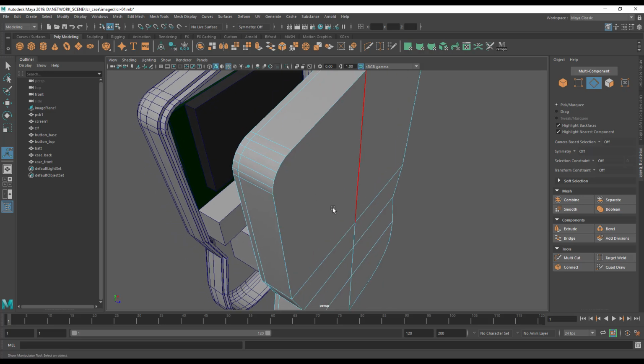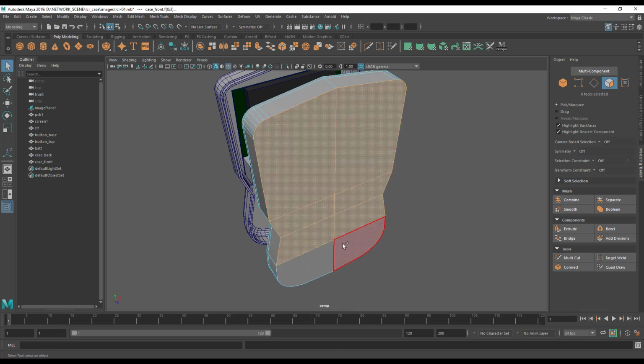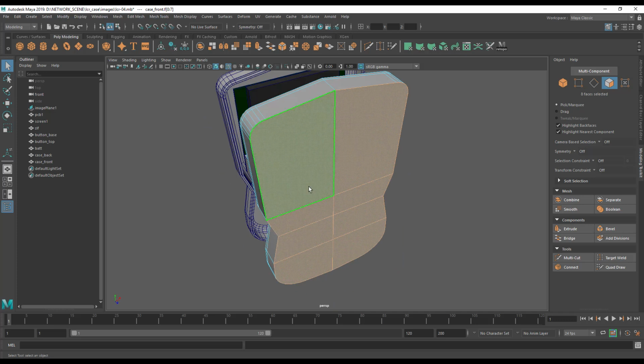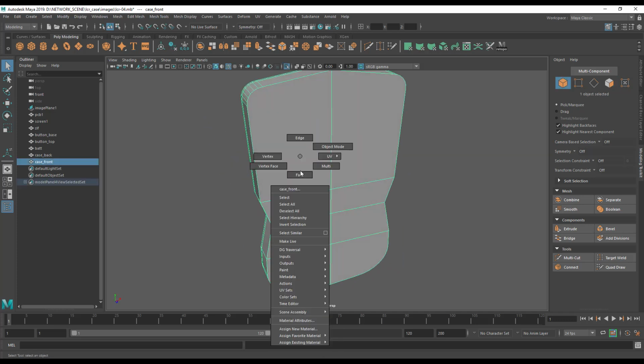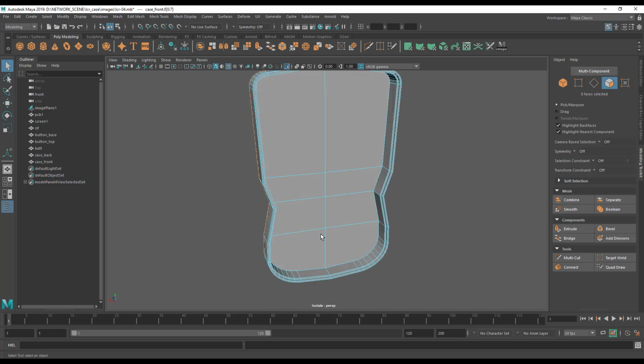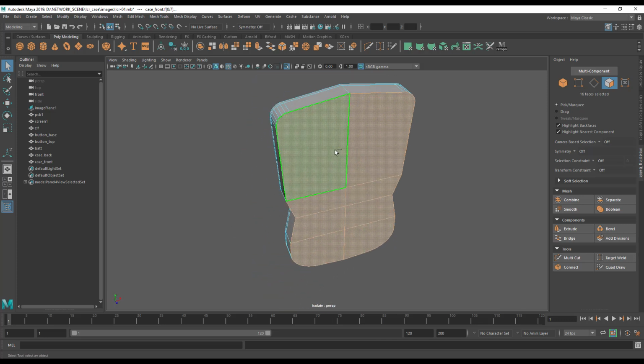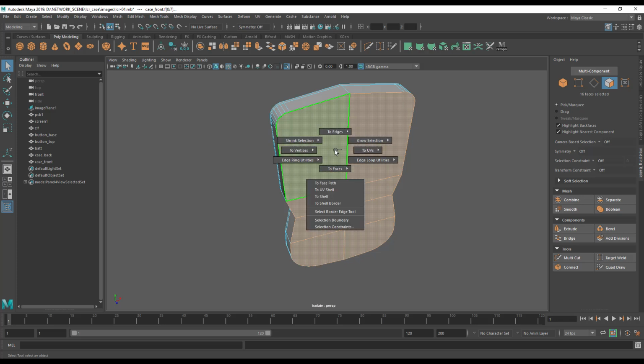Now I'm going to do the same thing. I'm going to select all the faces on the back, exactly the same procedure we used for, in fact before I do that, let's isolate this, so Control 1, so we're not fighting with the viewport all the time. We're going to use the same procedure we did on the back of the case, because we want to keep that consistency of thickness, very important for 3D printing. Now I can come up here with the control button and go to edges,